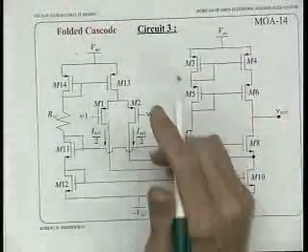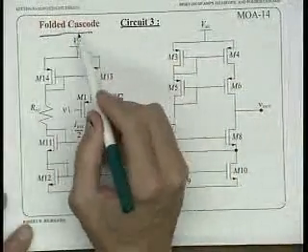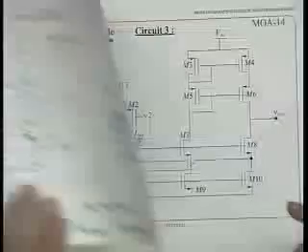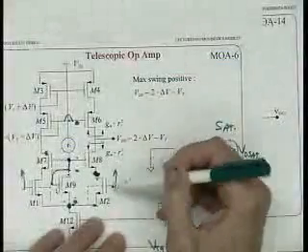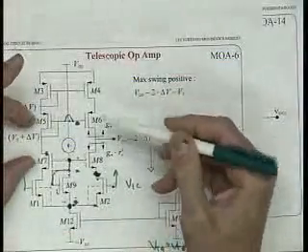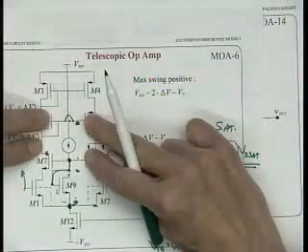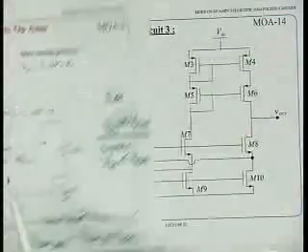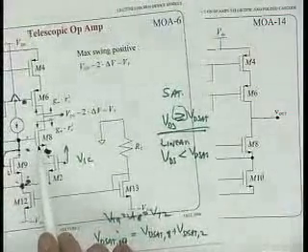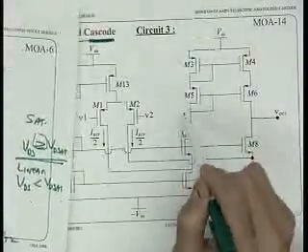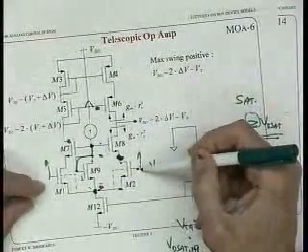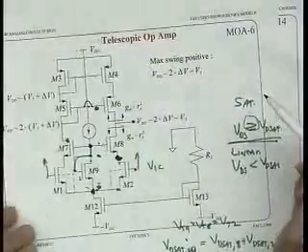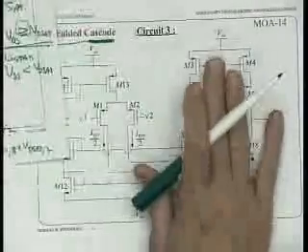This circuit here, this thing called a folded cascode, notice there's cascode sitting in this term, and this telescopic thing is basically just a cascoded load with a cascoded driver device, right? I mean, M8 and M6 are just two cascodes over just a straight old differential pair. So this circuit and this circuit are very closely related. What's really happening is we're doing something which allows us to get a better swing at the output, and particularly we get away from this dependence, having to worry about this common mode swing here. Okay? So how do we get from here to here?